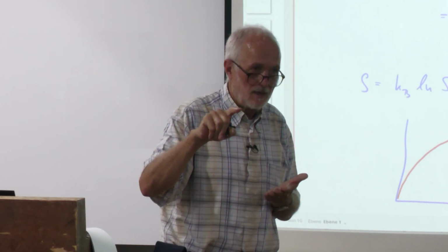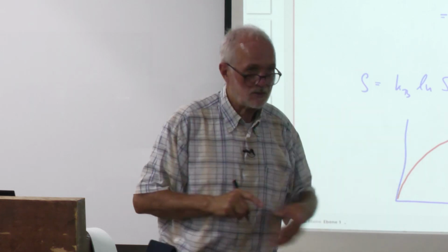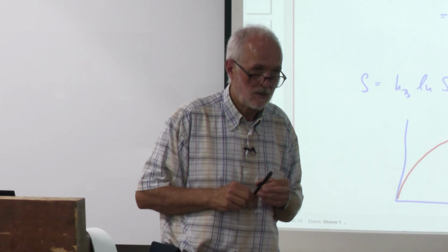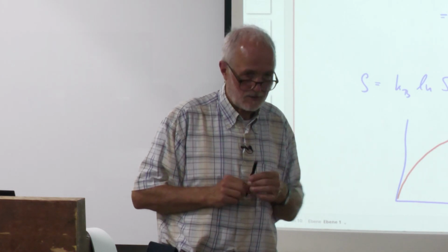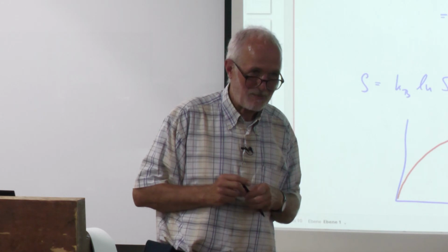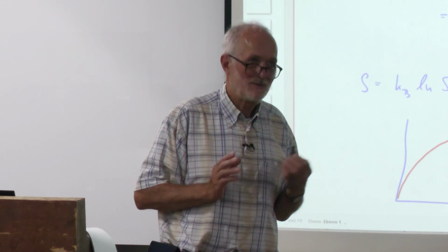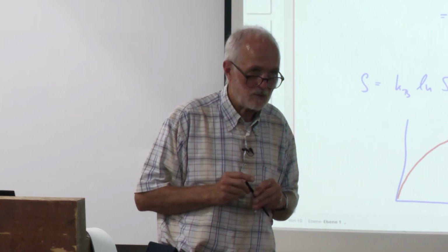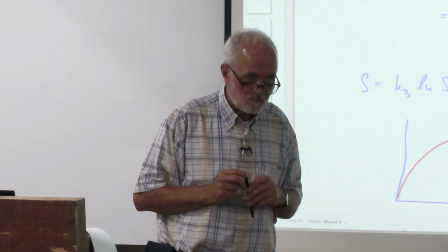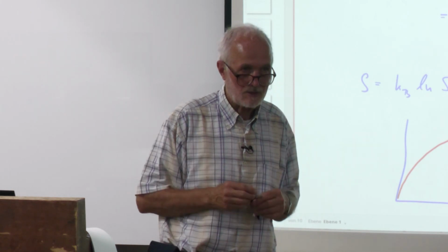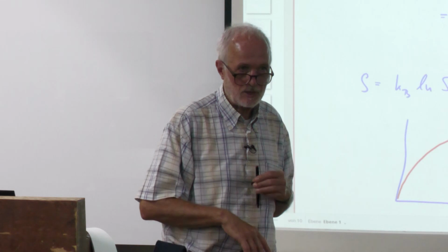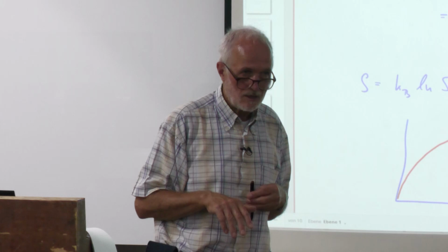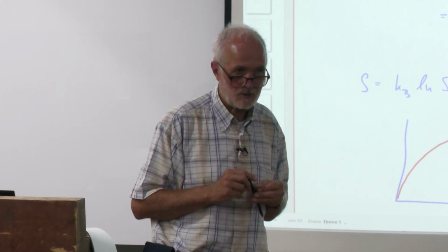And this is because you have also these large contributions to entropy by vacancies. As Guru said, and I come back to this, the typical vacancy concentration of most metals at the melting point is about 10 to minus 4, perhaps 10 to minus 5, because you have this entropy. But of course, if you go to lower temperature, entropy plays a less important role, and then the contribution gets smaller.